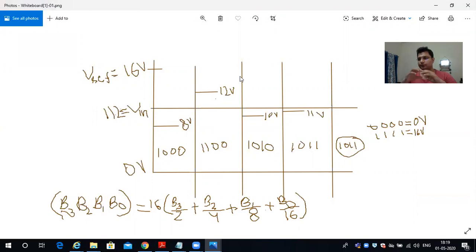So it's a 12-bit successive approximation algorithm which we are using with our core LPC1768. For understanding purposes, here we are understanding it through a 4-bit successive approximation algorithm. So the resultant final digital output will be in 4 bits.